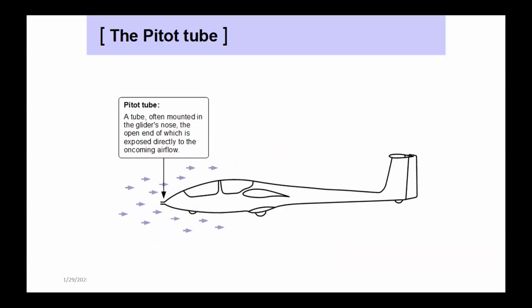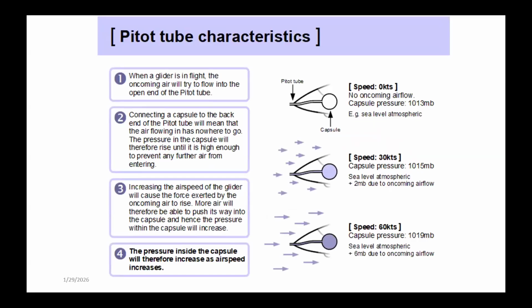Pitot tubes are often mounted in the nose. It doesn't have to be a straight tube all the way back to the airspeed indicator. Some aircraft have a closed chamber, and because we're measuring pressure, not flow, when that chamber comes up to pressure, that's what they're measuring it against. There is an alternative location that shows up on the vertical, possibly on the vertical and the horizontal tail, depending on the kind of probes you have mounted back there. So again, we're talking pressure, not flow.